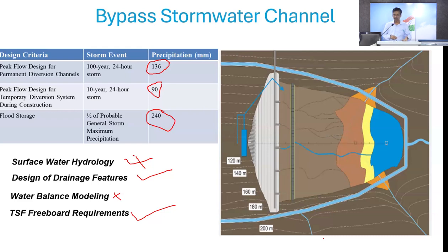So when somebody is dealing with that type of work, this aspect is important, because many times we say it is dynamic, that in only 1 year this mining will be put out, then our drainage system will be changed. But this aspect we need to take care of, particularly drainage for the present, how to divert water, and what the freeboard requirement is for the tailings. And this aspect also applies to overwater dumping.